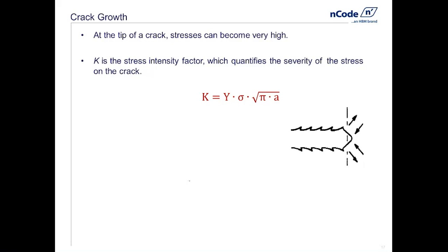So we introduce this thing called the stress intensity factor, which is not infinite for every crack. Stress intensity factor is related to a geometric factor, Y. You can look this up in a handbook or use FEA to derive this. It's also related to the nominal stress, not the stress at the crack tip. Remember, that's not very useful because that goes to infinity supposedly. So this is the nominal stress, P over A or My over I, and also related to the length of the crack. So the longer the crack is under given stress, the more severe problem we have.